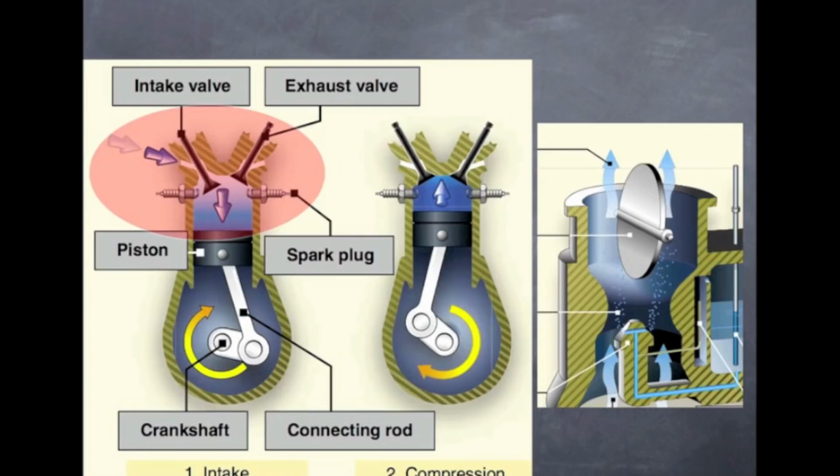As the cylinder moves downward, it creates a vacuum, or it'll pull that volume of air through. The throttle, of course, does not allow all the air it can through there, the ambient air pressure. It actually chokes off some of the air. In other words, almost starving the engine, even at idle thrust, or idle power, excuse me.